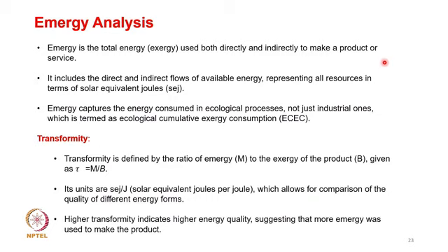Emergy is the total energy, in the sense of Exergy, of course we are only considering the Exergy, not the free energy, used both directly and indirectly to make the product or service. In Exergy we typically use only direct contributions. Here we also consider the indirect contribution, making this a wholesome metric that is helpful to analyze. It includes the direct and indirect flows of available energy, representing all resources in terms of solar equivalent joules.